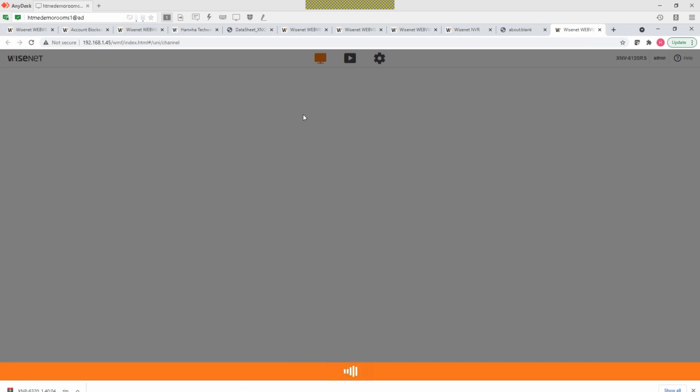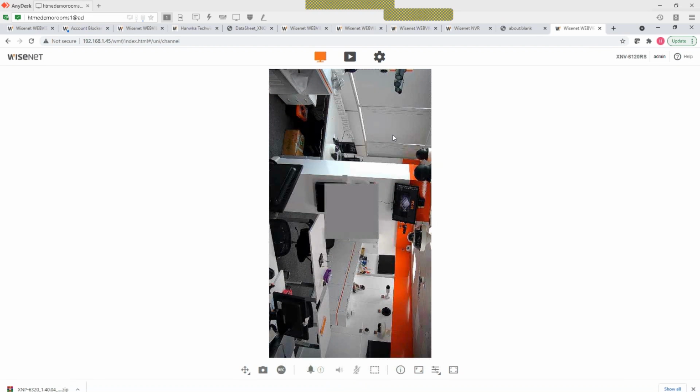All right. If you're going to use hallway view, you have to also manually rotate the camera lens by 90 degrees and then also apply hallway view in the camera web page. Some models you have to do that. You have to wait for roughly 30 seconds because the camera will restart. Okay, all right, the camera is now online.